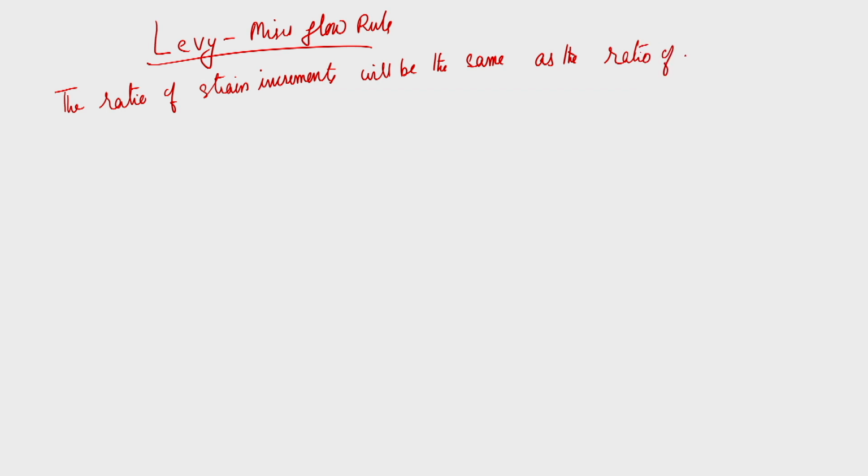So, this Lévy-Mises rule states that the ratio of the strain increments will be the same as the ratio of the deviatoric stresses.